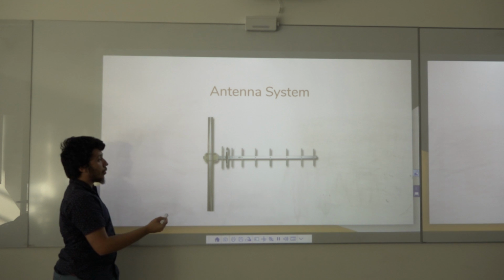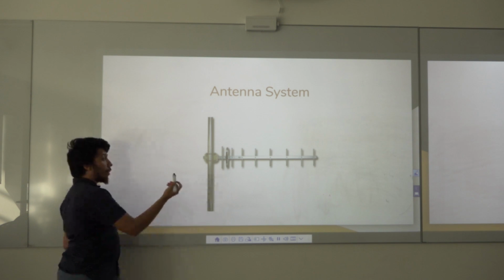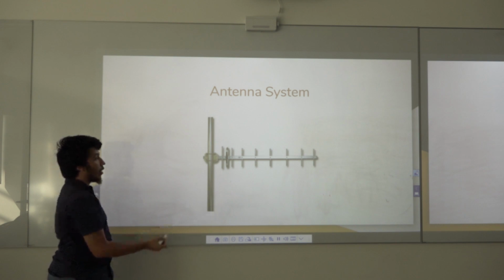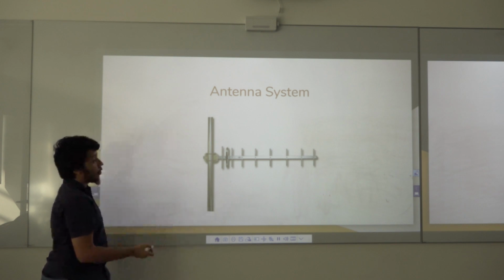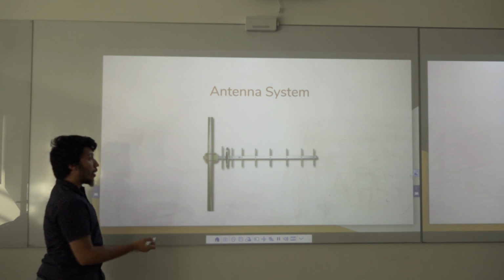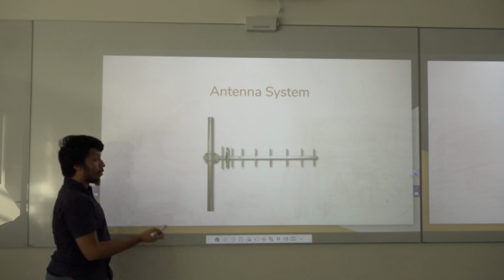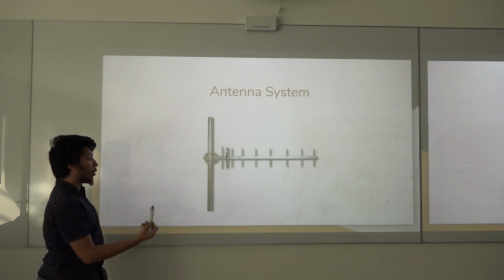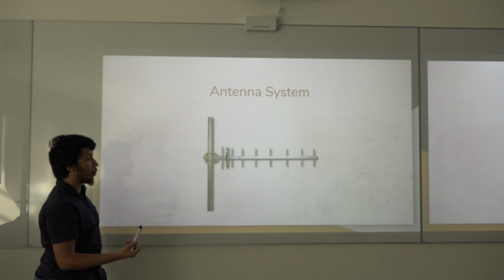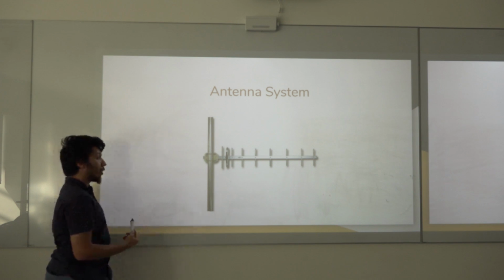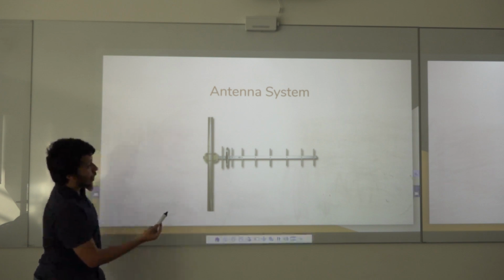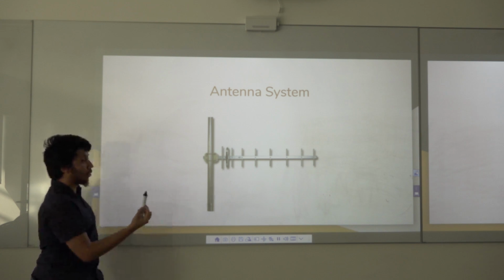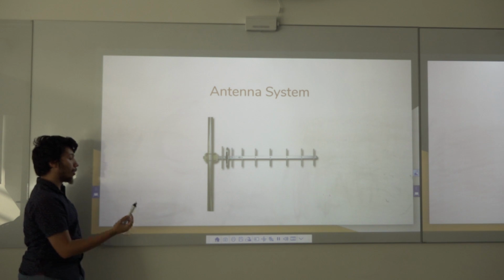All we need to do for the system is to take the difference of our reference signal to our received signal from our Yagi antenna after some normalization of the signal strengths. As long as the difference is greater than 0, then we know that the motor has to rotate in order to point the antenna towards the direction. What we eventually get is behavior that leads the antenna around a circle until it points towards the signal source.